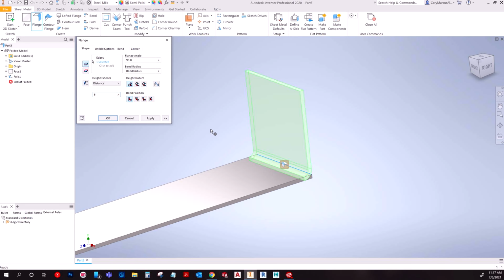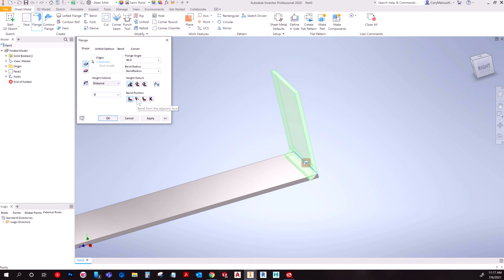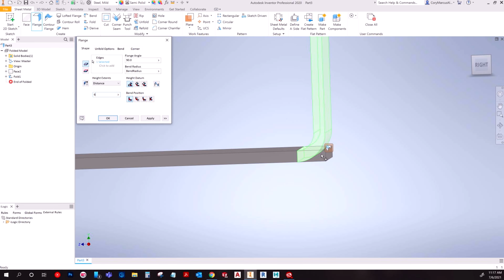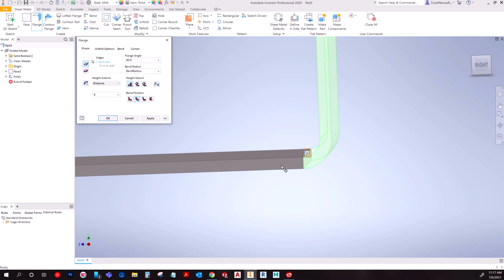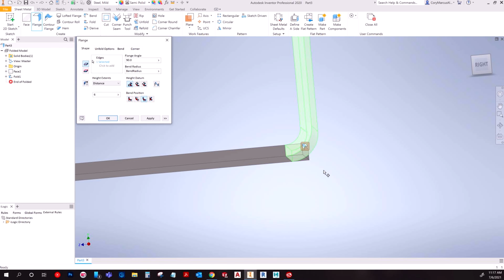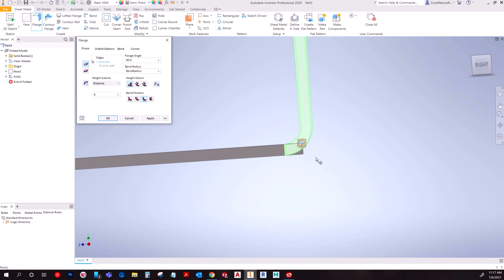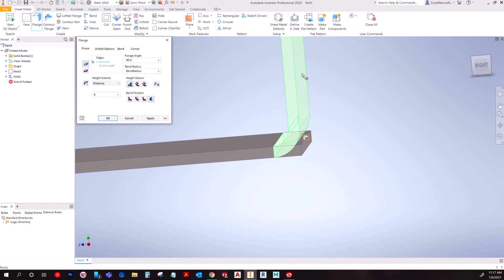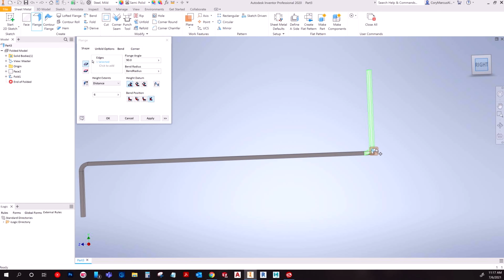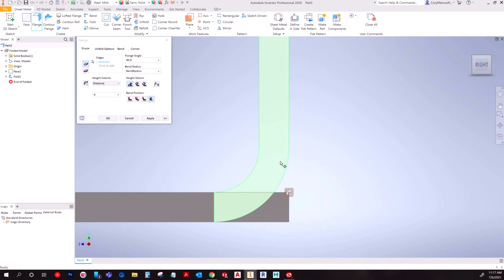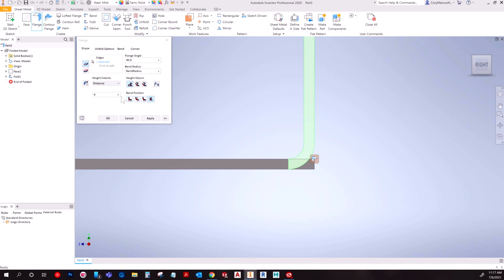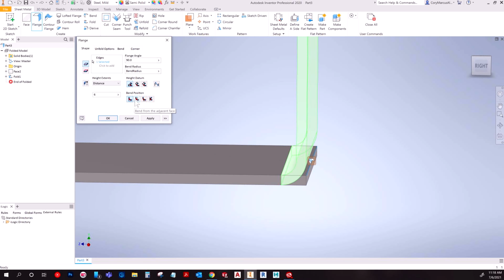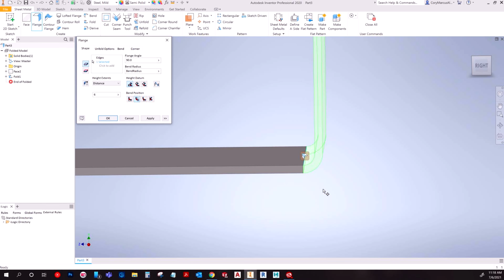And then you have some other options. You can change the position where it bends from. So I mentioned here it could be from there. You can also move it to the end of the part. You could move it to where it's the inside face. So you've got some options. I don't really think I ever used bend tangent side to face, but it's pretty much the extent, as you can see there. So actually that would be a great one to use probably. But the default is usually never the ideal one in sheet metal features for whatever reason.